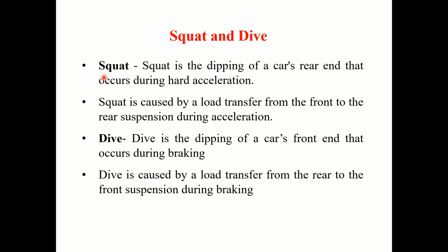In earlier classes, I explained what exactly we mean by squat. Whenever a vehicle is accelerated, the dynamic load from the front gets transferred to the rear so that the rear portion dips and the front portion lifts up.